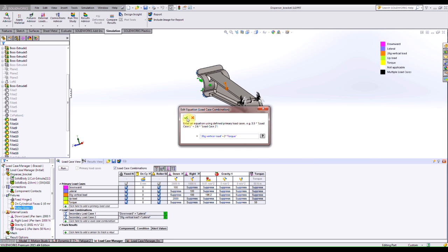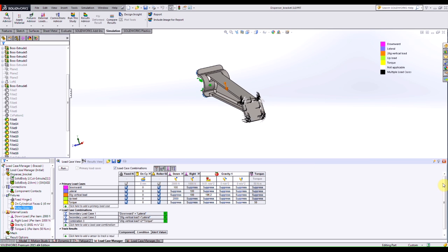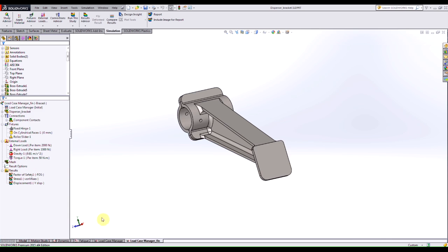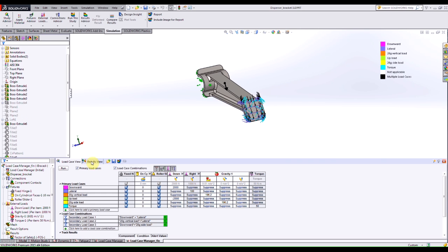If I define that interaction, you see that the last thing we can do is create some kind of result. We want to know how these load conditions affect any potential stress or any displacement that's being applied to this model. In this case, you add that by defining sensors. After you define your scenarios, you can then run the analysis, and if I switch over to my completed file set here, we can go to our results view.